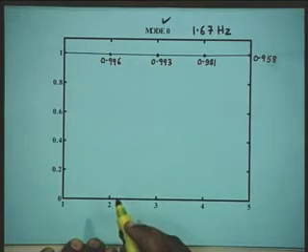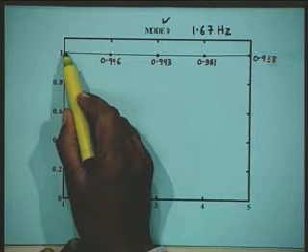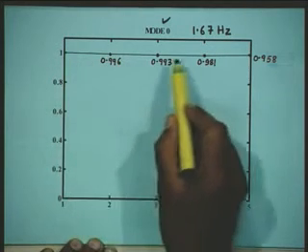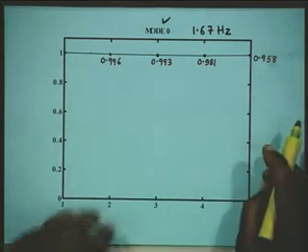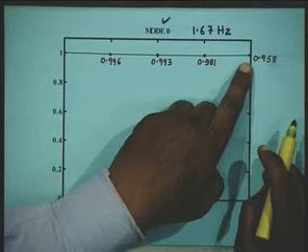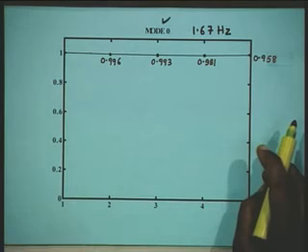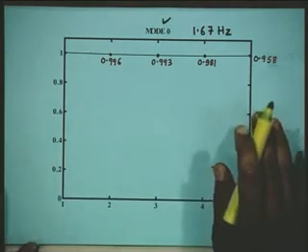This mode 0 is the system mode whose frequency is 1.67 hertz, and it has the magnitudes 1, 0.996, 0.993, 0.992 and 0.958. More or less all the state variables associated with this mode have the same displacement. This 0th mode, or system mode, represents that all the masses rotate together with respect to the system.